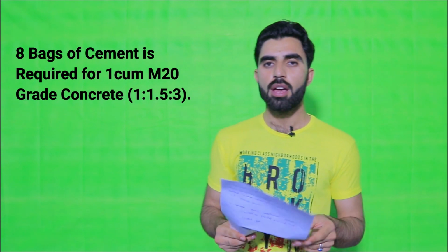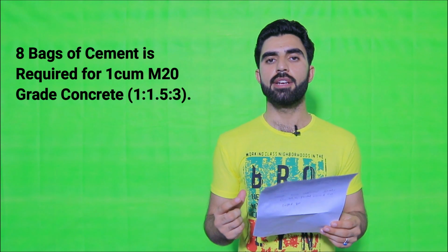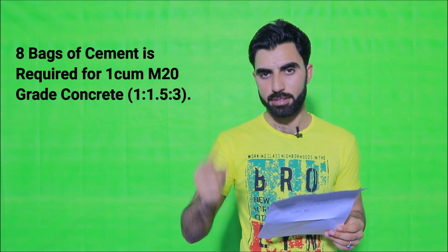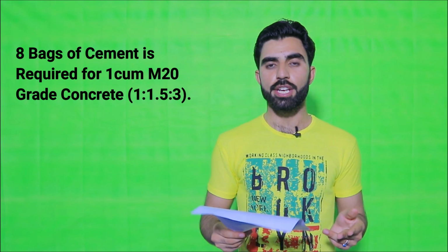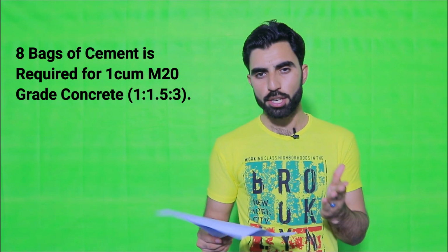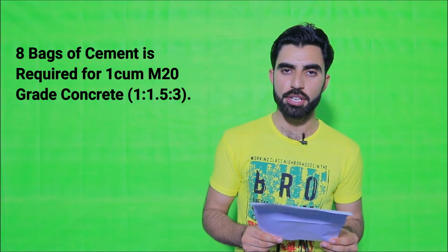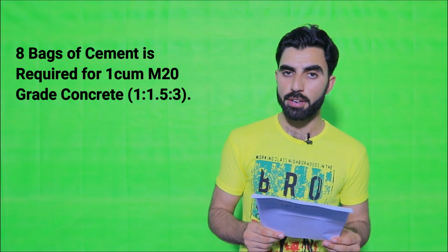Okay guys, the fifth one is that 8 bags of cement are required. If someone asks you how many bags of cement are required for 1 cubic meter of M20 concrete, 1:1.5:3, for M20 grade concrete, for 1 cubic meter we require 8 bags, and each bag weighs 50 kg, right? Guys, the last one is very useful.